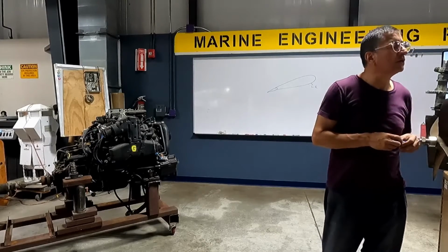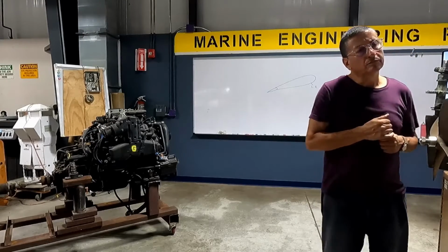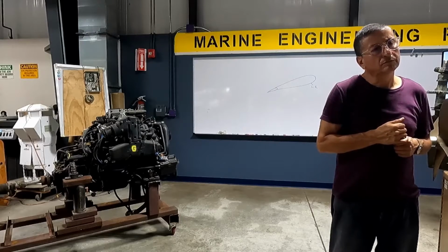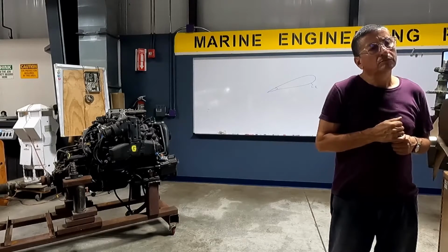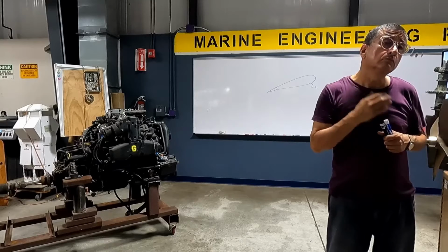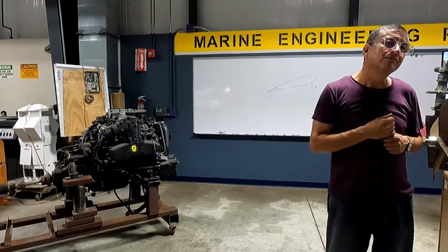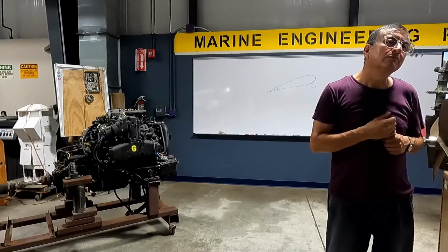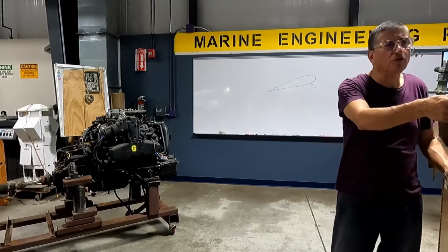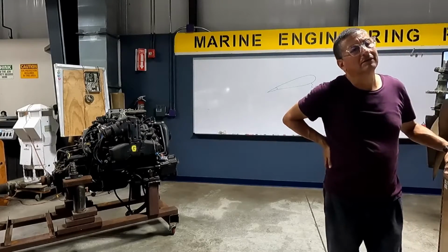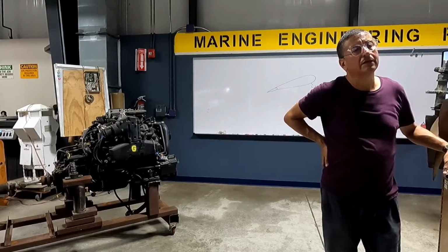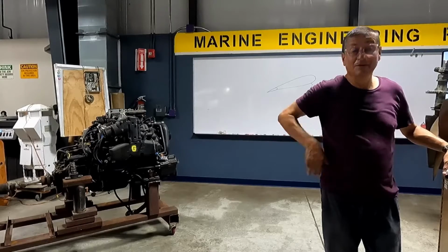Correct. Exactly. I took a 65 recently up to DC, and we hit bottom in the sound, and a diver went down there and got a whole video of the prop. I dove down myself as well, just with goggles, and the propeller is in perfect condition. There is no bend. But after we pass like 1400 RPM, you feel the starboard engine dance, and we still can't figure it out. So the starboard side, I think we have to remove the shaft and check it. Yeah. Now we are going.